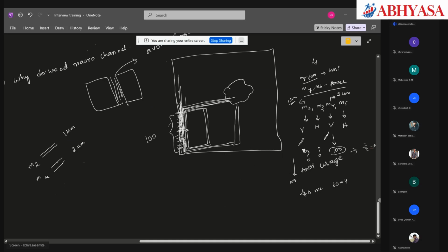Now we don't know how the tool is going to route, whether 100 in one layer or 40 and 60. Let us say, for example, worst case scenario, the tool has routed all 100 vertical nets in M2. In M2, you must have seen that there will be tracks.